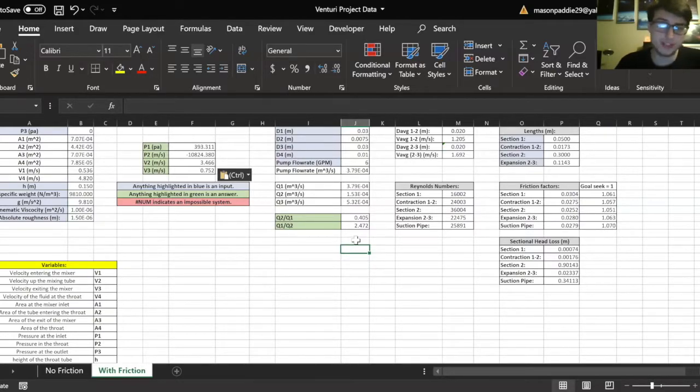This is one of the major sources of error in our Venturi design because whenever we started the Venturi, it originally started spewing water, and we had to use a rubber sealant in order to cover the Venturi. Now, any air holes that are in this Venturi will cause extreme fluctuations in our results, and this is what is causing the fluctuations in our results.